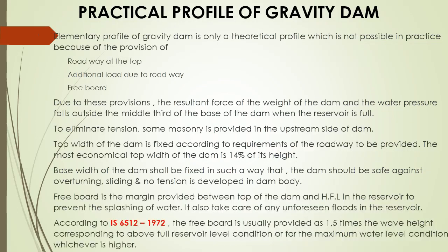Now we are moving to the practical profile of gravity dams. The elementary profile of a gravity dam is only a theoretical profile which is not possible in practice because of the provision of a roadway at the top, additional load due to the roadway, and freeboard.